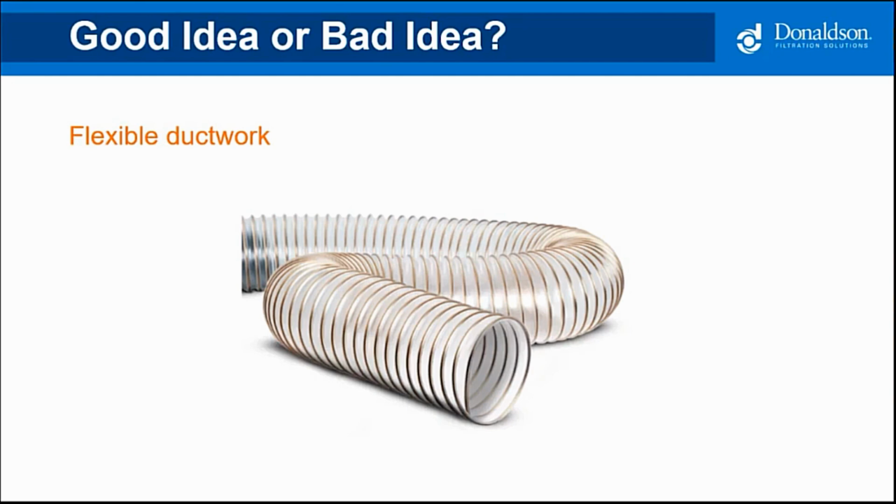But you run into situations where, if you remember those articulating arms I showed, it has elbows that are covered in flexible duct, allowing you to move the hood around. Or you could have a hard automation hood that is on a piece of equipment and that we may need vibration isolation. And so there may be a reason that we have to use flexible ductwork.